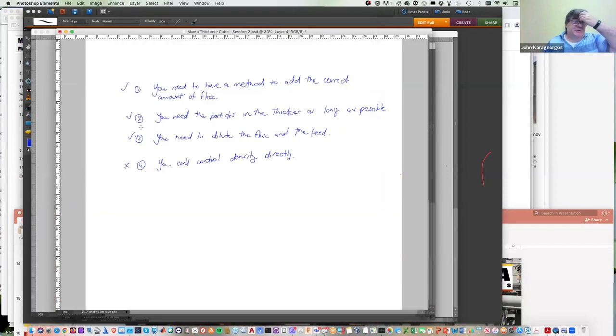So we're back to achieving decent thickener control. You need to know how to add the right amount of floc. You need your interfaces, and at the moment, the diver type instrument, the diver sub, we have another one called the sub, is the only thing in the world that we know that does this consistently, day in, day out. If there was something else that was better, we'd be using it, right? And Matt would be selling it.